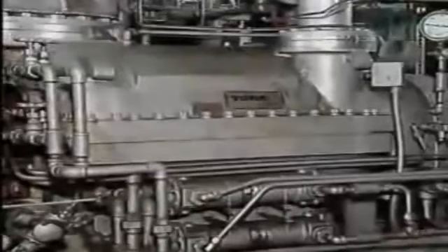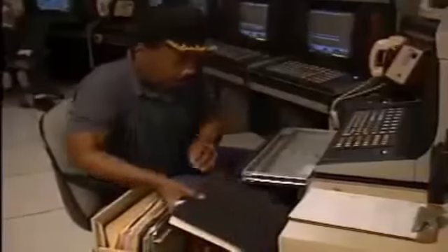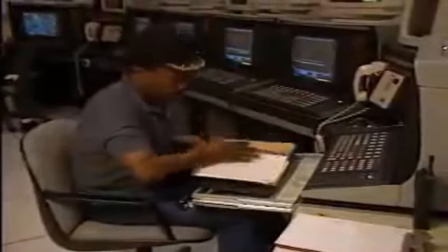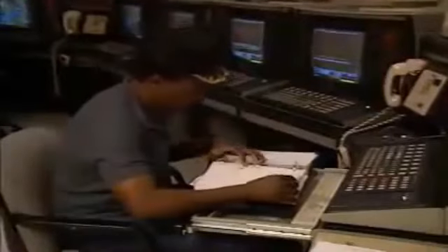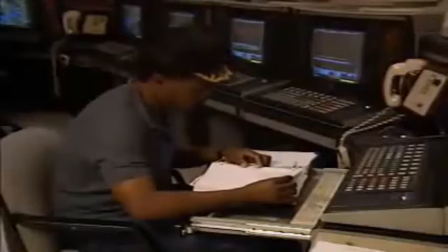The vibration can be severe enough to seriously damage a compressor. Critical speeds are often identified in a compressor's operating procedures, and they occur when the compressor is at less than full operating speed. When a critical speed is reached, the ramp rate is usually increased to pass through the critical speed as quickly as possible.